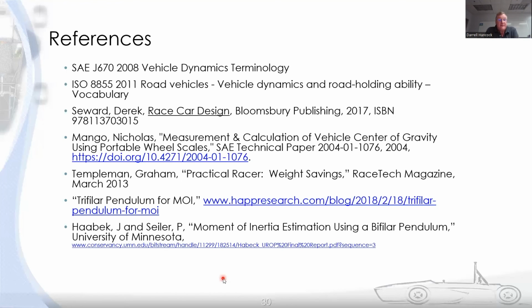If you have a big rear wing with movable elements, be aware that raised your center of gravity. And as a judge, I might say, what was the trade-off there, right? You gained some downforce, but you raised your center of gravity. And you put a motor up there to rotate your flaps to give you less drag in a straight line. What was the trade-off for the weight of that motor being mounted up high on your rear wing?